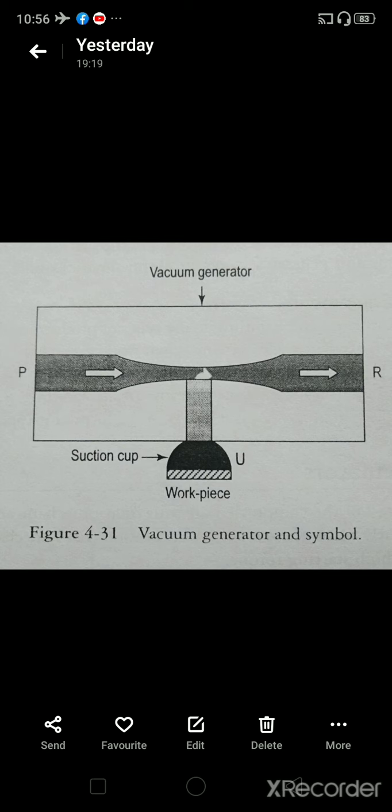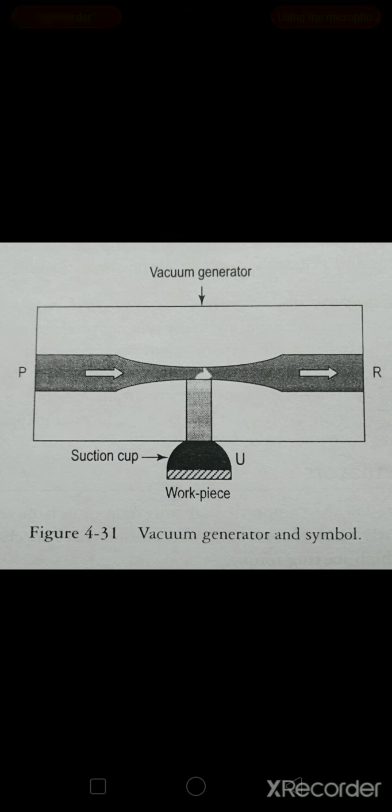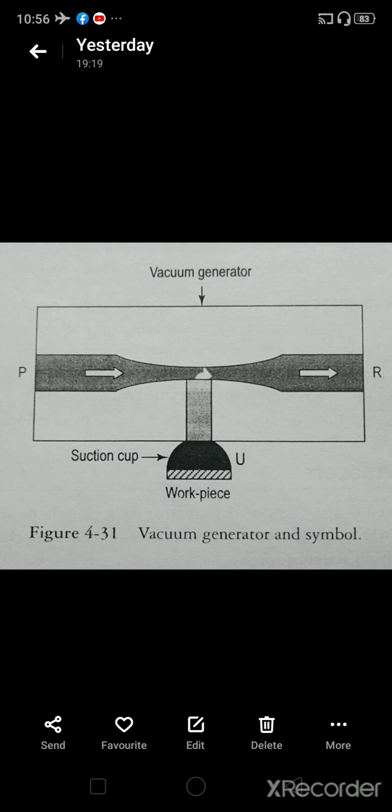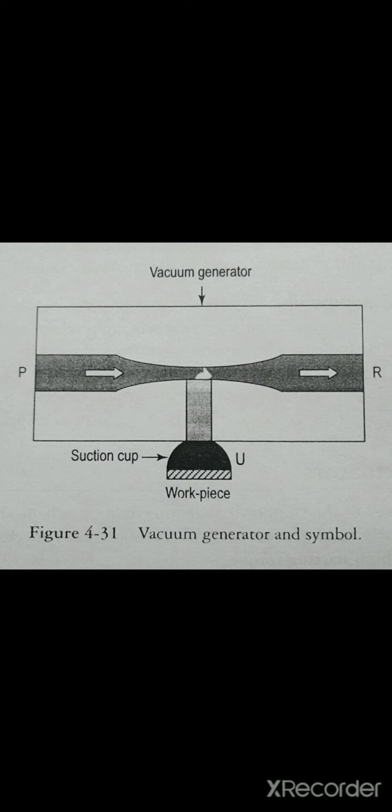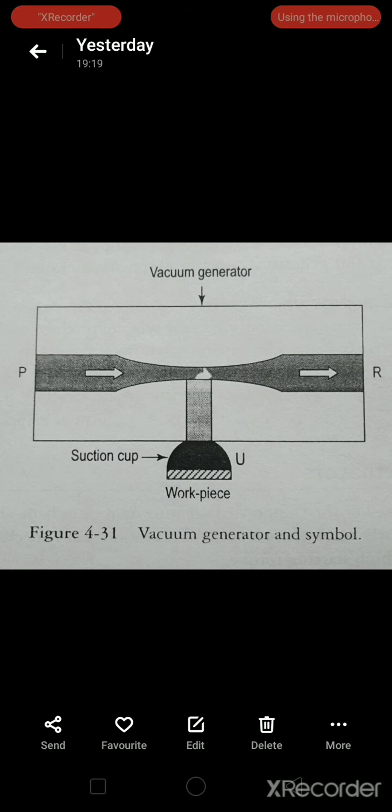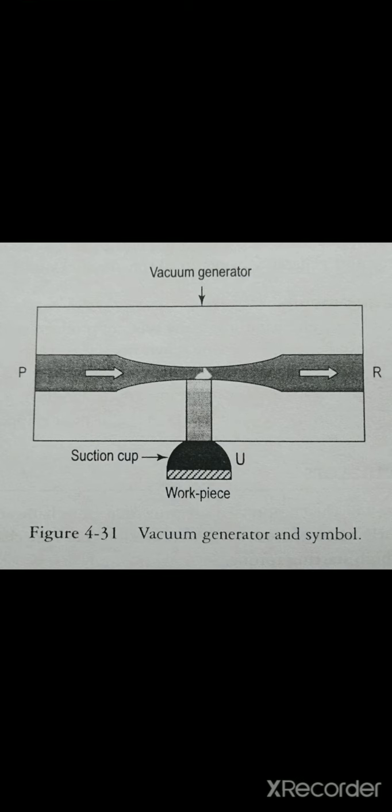If a workpiece blocks the suction cup, the vacuum produced in the suction cup grips the workpiece. If a pressure of 6 bar is applied, typically a vacuum of 0.8 bar is generated. A silencer is integrated in the housing. So various types of vacuum generator are available, all of which can be equipped with various types of suction cup to obtain the specified values of suction force.